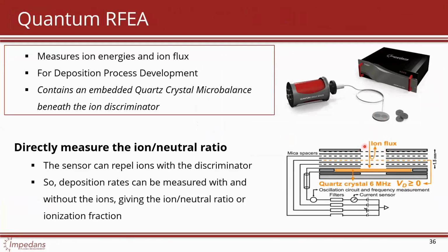So in reality, when you're using these sensors, you have to have a reference process. You would run a reference process, and then if you're depositing, after a certain amount of time, rerun the reference process and see how much your flux has dropped, which in other words is telling you how much clogged this is. Now, when it comes to ion neutral ratio, it doesn't really matter anymore. If the sensor becomes more clogged up, the ratio is still the same for what's deposited. So that's fine. It's only the ion flux that you have to worry about for sensor to sensor repeatability.